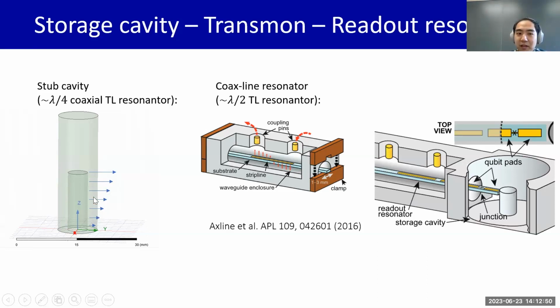And this top, so most of the E field is confined in here as the λ/4 coaxial transmission line, basically, that has E field structure like this, shorted here and close to opening here. And the seam exists here, which is physically far away from the E field. And there's an exponential decay of the E field due to this tunnel cutoff frequency.